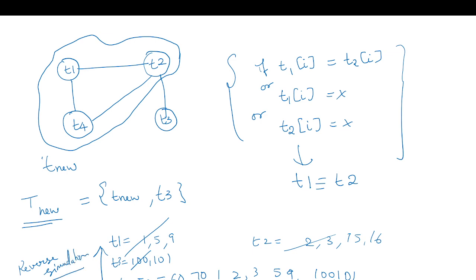So these are the two methods by which we can reduce the test pattern size: reverse fault simulation as well as the test compaction, where we have a compatibility graph and we merge based on the compatibility.